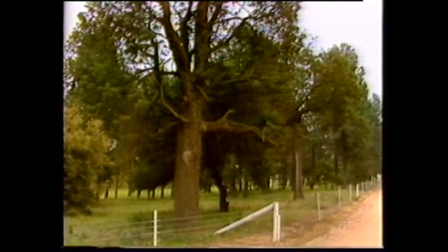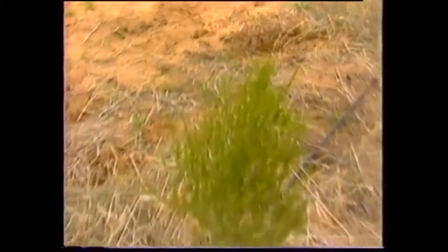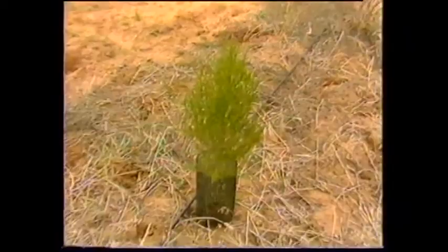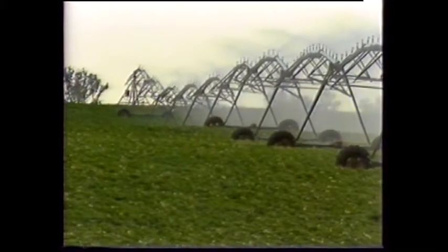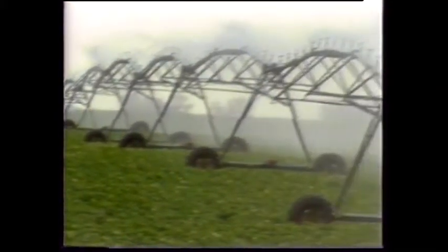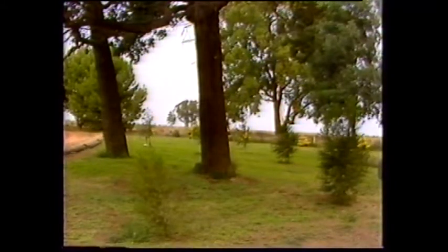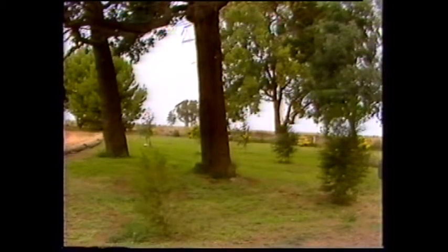Now let's look at woodlots and erosion affected areas. In areas very badly affected by soil erosion, replanting with trees or shrubs may be the only solution to the problem. This may mean taking that area, say the upper slopes of a sandhill, out of production altogether in order to stabilise it with trees. The incorporation of trees into a revegetation program gives long-lasting protection to both the soil and other vegetation such as